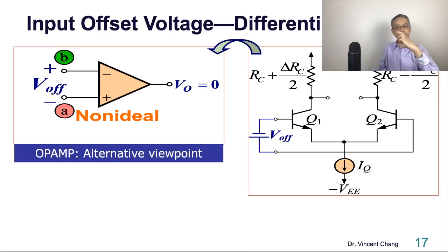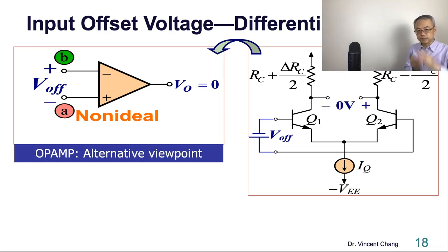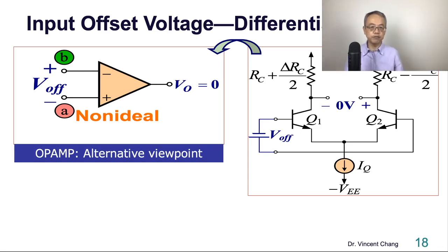So when you apply an external voltage so that the output offset voltage becomes 0, then the applied voltage is defined as the input offset voltage. This lecture is only focused on the concept, to make sure you grasp how to calculate, where to start, and what the key steps are.